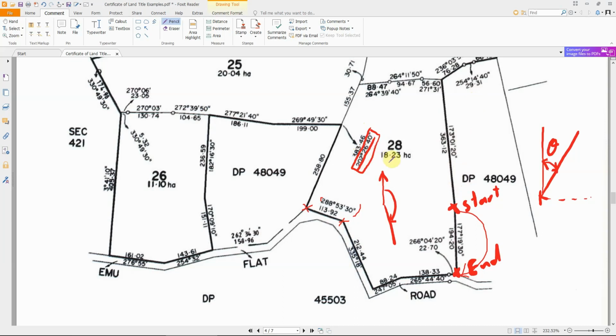This means if I use this number blindly, without thinking through it, without understanding the concept, and I enter these values on the software, as you'll see in a minute, the software will simply draw a line like this, rather than like that, which is incorrect. So it's important to understand when you look at this number here, you should evaluate what the value should be. I'm looking at the line here. If this is the starting point and this is the end point in my work, that means this angle should be between 0 and 90. If not, I find that it's not like that.